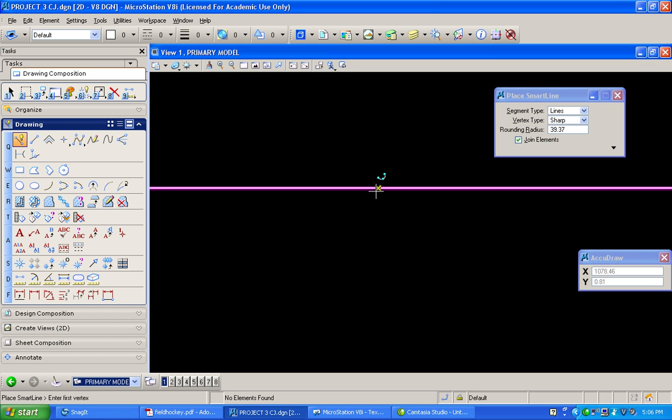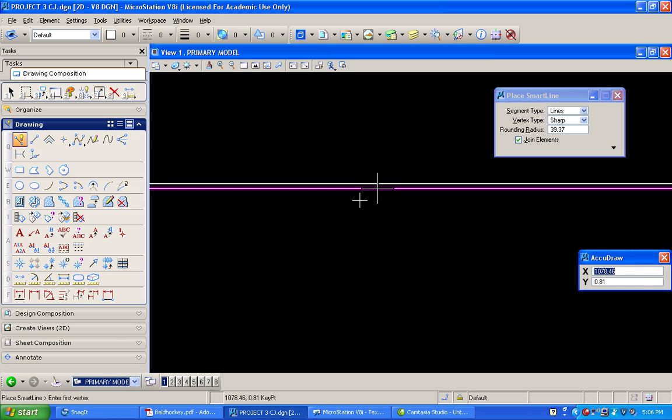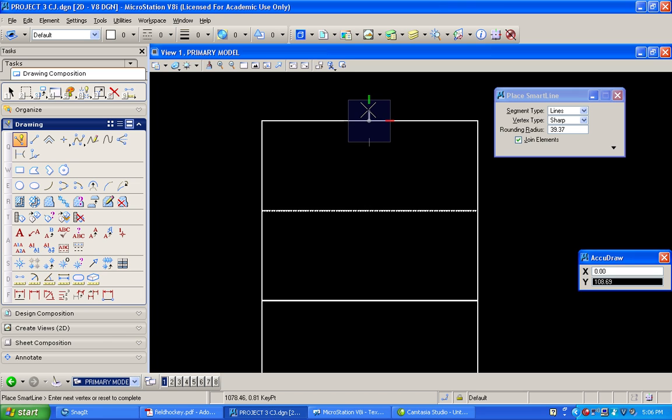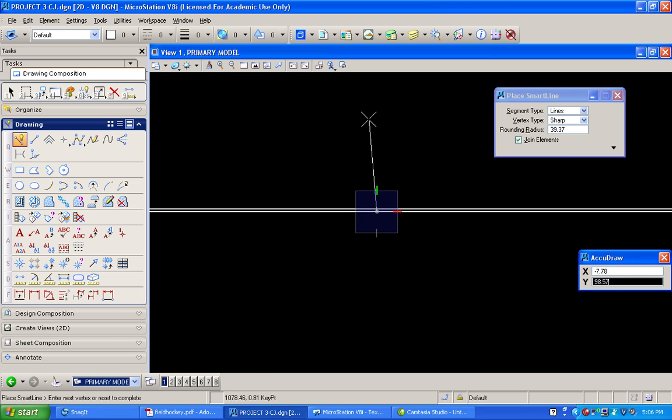Settings. Oh, I bet my working units went back to inches. Aha! Because I changed the name of it, I didn't do a save settings previously. My bad again. Believe it or not, I haven't been drinking today, so hit OK. File, save settings, good deal. I'm sure some of you already picked up on that.